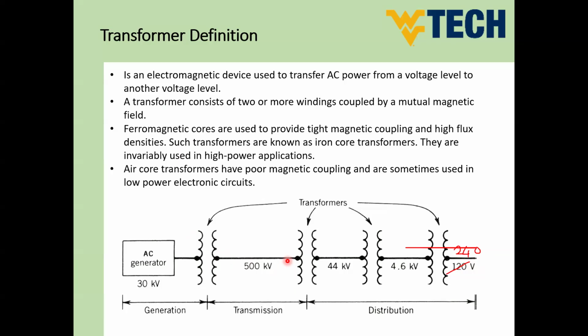So copper loss in any windings or devices is the summation of I square R. The cables or transmission lines have resistances, and the power loss across these resistances is I square R. So if the current is relatively high, the power loss would be very high. For that, we prefer to use high voltage levels before transmission in order to reduce the amount of current transferred.